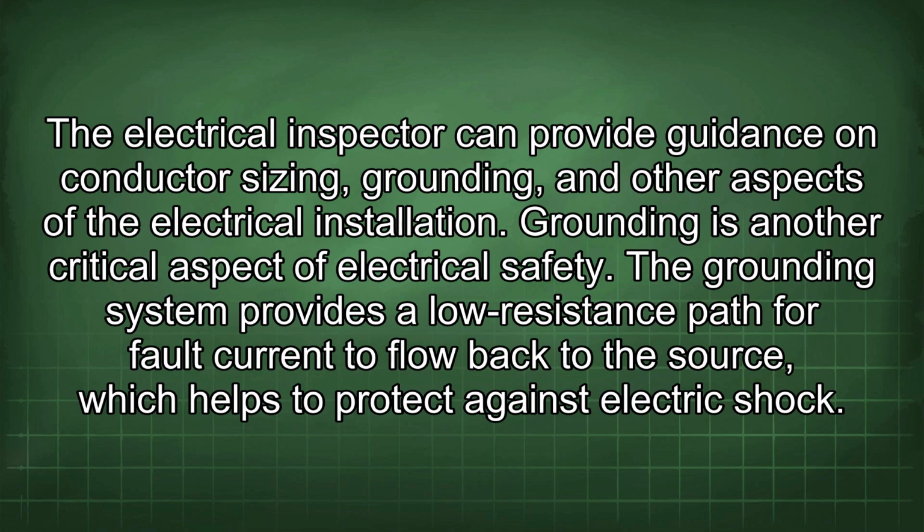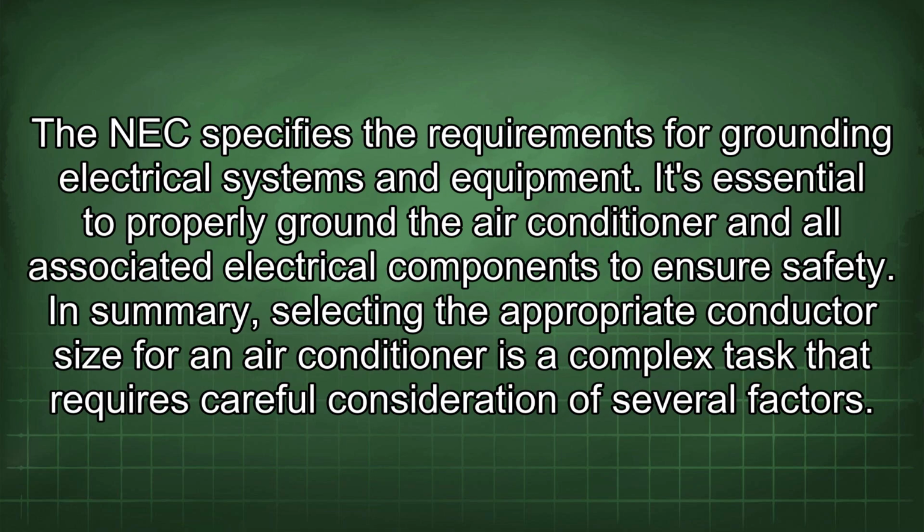Grounding is another critical aspect of electrical safety. The grounding system provides a low-resistance path for fault current to flow back to the source, which helps to protect against electric shock. The NEC specifies the requirements for grounding electrical systems and equipment. It's essential to properly ground the air conditioner and all associated electrical components to ensure safety.